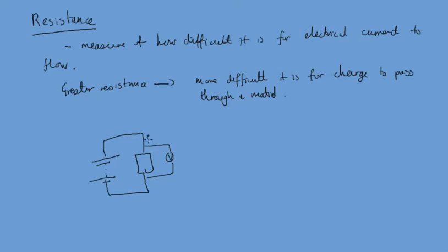You've got our wee electron coming through here, and it gets to this resistor, and there's resistance in here. So our electron has to be pushed through here, and to push through here, there's some energy being used to pass it through the resistor. So we then see this drop in potential difference at this point in the circuit.